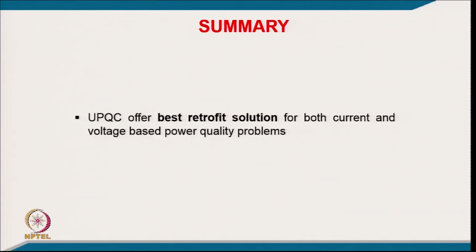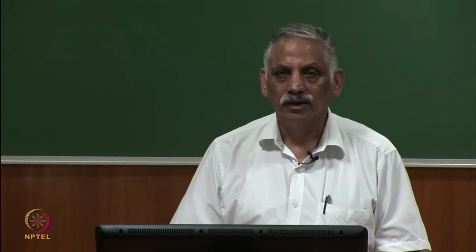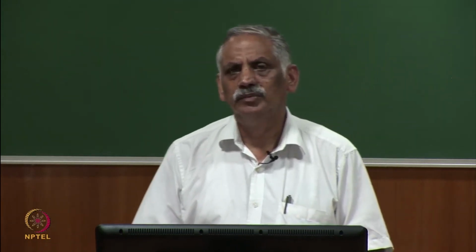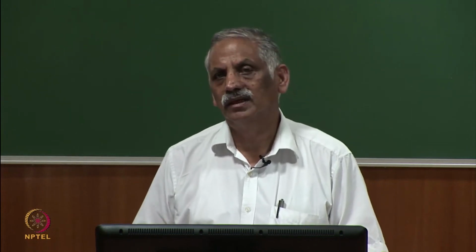So, it is capable of supplying the regulated voltage across the load and maintaining the unity power factor on the grid side, in spite of the voltage being unbalanced or the current also being unbalanced. Well, with this now we would like to summarize this lecture on unified power quality compensators. The UPQC offers the best retrofit solution for current and voltage based quality problems. We have discussed the configuration of UPQC. The best configuration among the various configurations is that we put the dStatCom or shunt compensator on the load side,